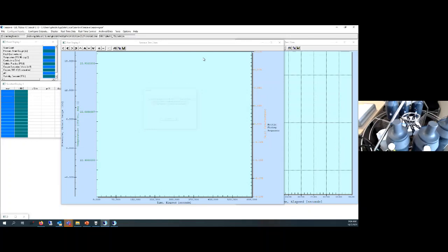Okay, I just flipped the switch to on my CTD, and so CSAVE is now collecting CTD data, but we don't see anything popping up in our displays, and we see what's called a scan length error at the top here. What's going on is because the output format is still set for what we need for auto fire, that is output format 4, that output format is not compatible with CSAVE, so we need to go and switch back.